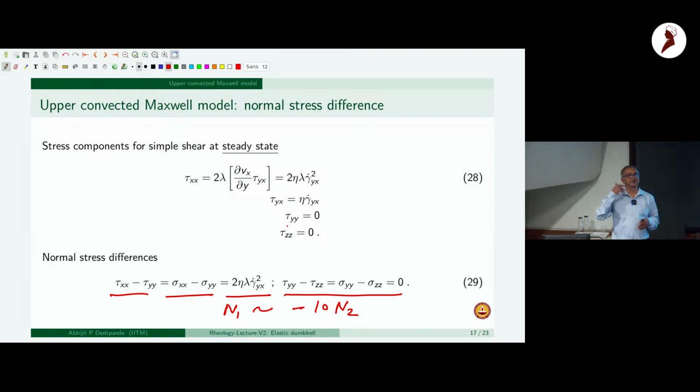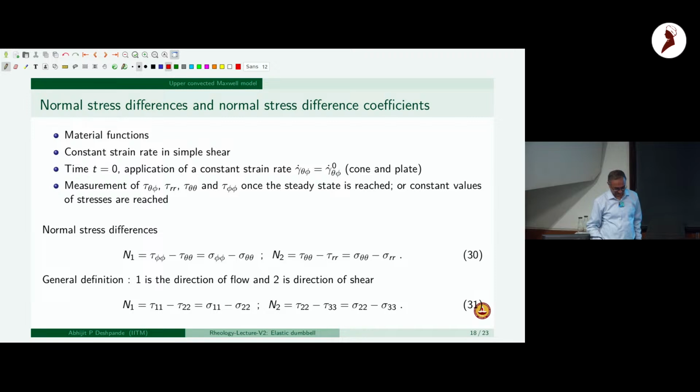So just the way our initial analysis of fluid mechanics starts with the Reynolds number as a non-dimensional parameter, polymer engineers would form a non-dimensional number with the normal stress difference and then say, okay, if it's below this, then I will get no problems in the polymer processing of these extensional flow situations. And so that's how historically this came about.